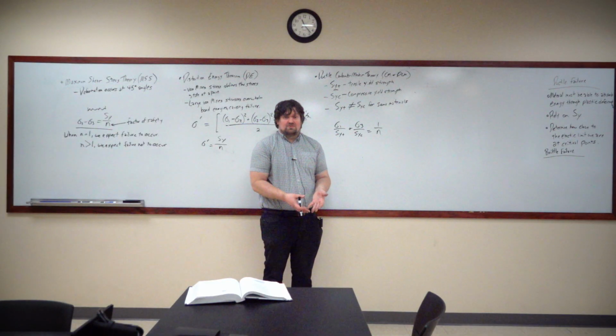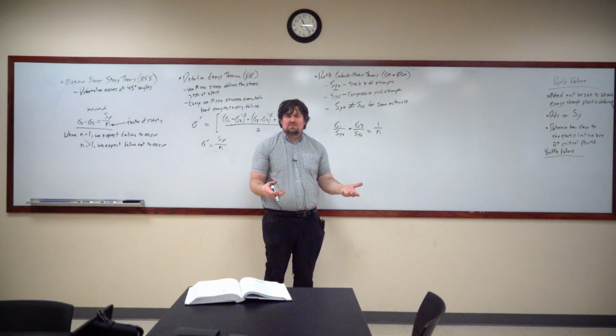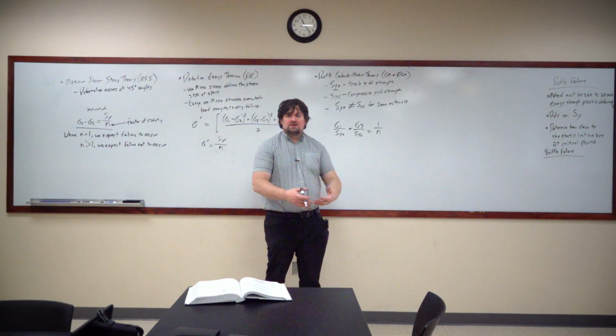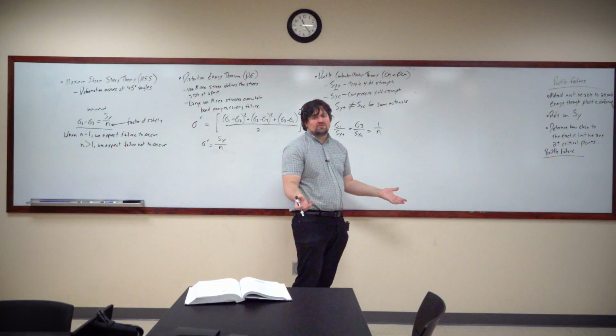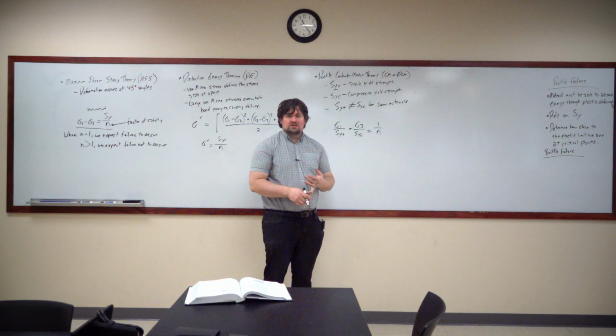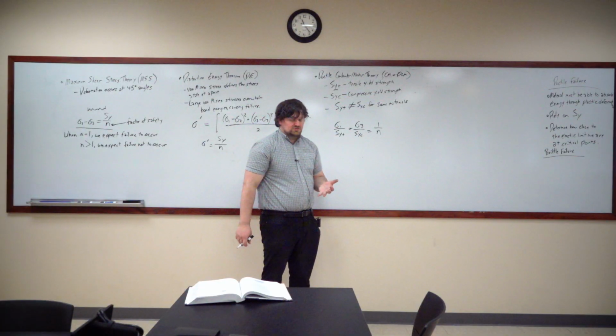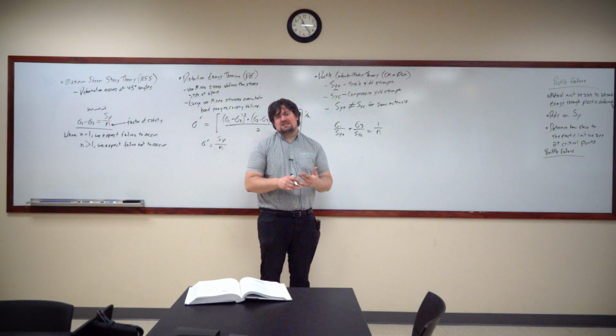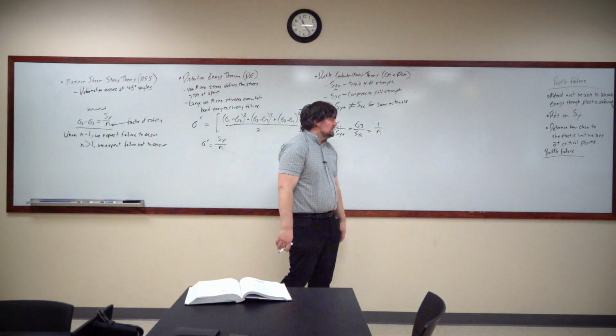Now plastic itself is called plastic because of its plasticity, but when it just shatters like that, that is brittle failure. We also see that metals that are really cold will experience brittle failure. We're also going to be talking about fatigue and how fatigue leads to brittle failure. But brittle failure, it's not exclusive to one material.